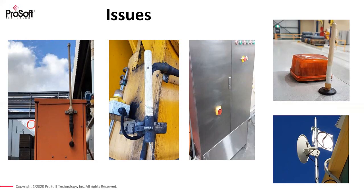Next picture with the big yellow steel structure in the background. So we've got an Omni mounted against a big yellow steel structure. Now what happens with the Omni is it sends out the signal in all directions. So the first thing, the signal hits this metal, bounces back and then starts interfering with itself.